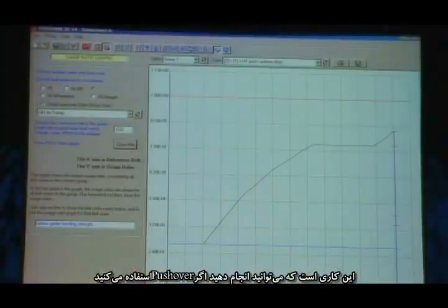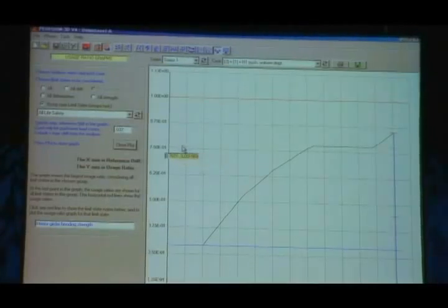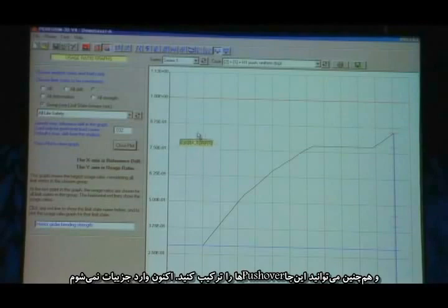One of the things you may notice is that in the dynamic analysis, these top two were reversed, but this is not necessarily a response spectrum that corresponds to those dynamic analyses. So this is what you would do if you're using pushover, and you can also combine pushover here if you want to as well. I'm not going to go into the details on that.